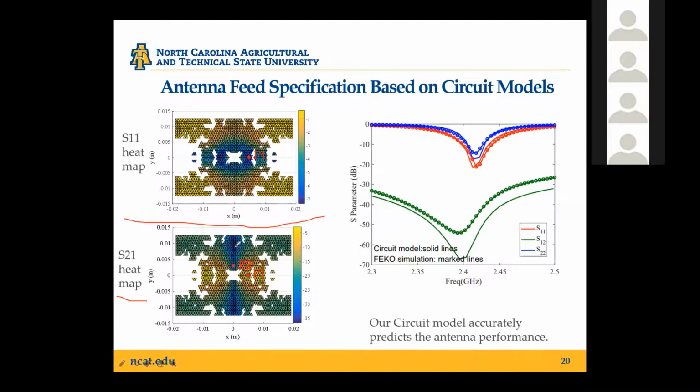And based on that, it indicates that if you feed your second port along the vertical line, you will have pretty good isolation between the 2 ports. So I picked my port 2 somewhere here, not only because it achieves pretty good isolation, but also because it's in the region where you have a decent return loss. Keep in mind, though, we have some data that shows you can pick any other feed locations as well, not necessarily the symmetric case. But I picked the symmetric case just because it's intuitively simple.